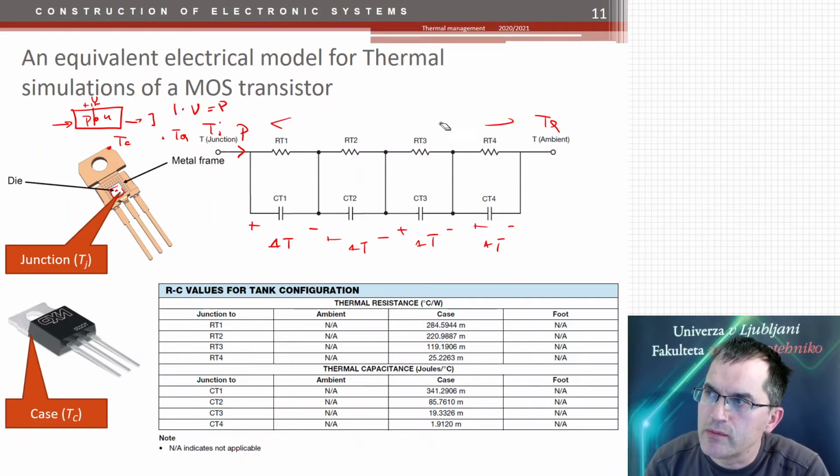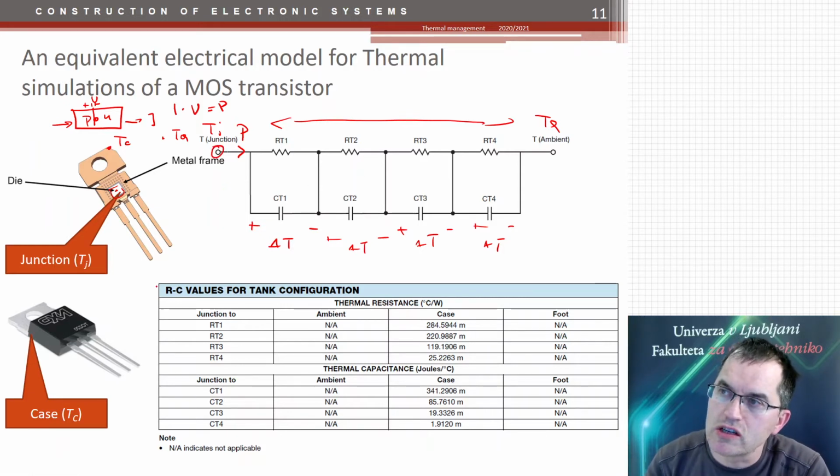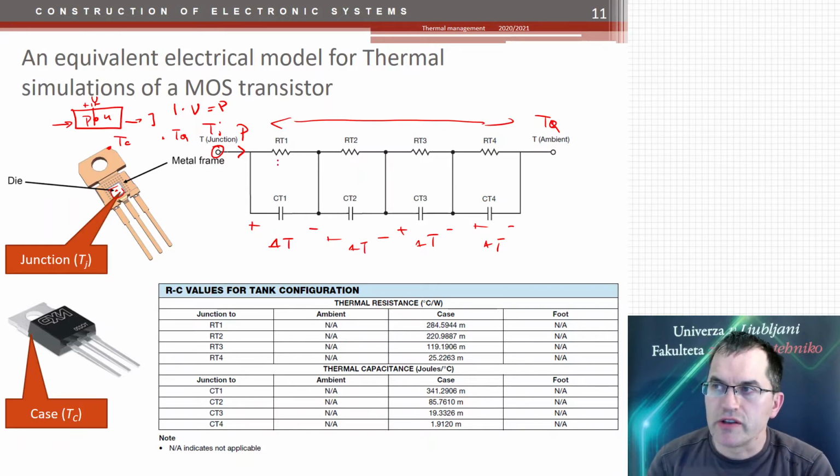And by using this circuit, we can calculate or even simulate, in, let's say, any electrical circuit simulator such as SPICE, the junction temperature if we know the power, if we know all these parameters, and if we know the ambient temperature. So these models are very well defined by manufacturers.